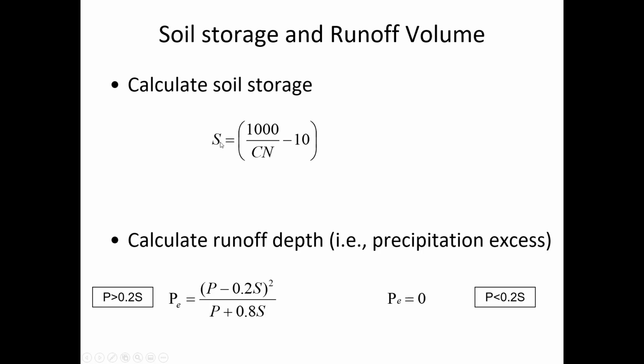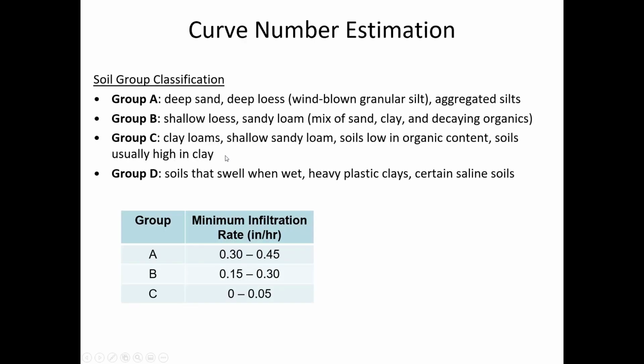So this is the NRCS equation, and this is simply how you calculate S. S has units of inches. Sometimes we use SI units, and you'd have to convert from inches of S into SI units, but these curve number tables are based on traditional units of inches for depth. So this is jumping ahead a couple of slides. If you've got them printed out, this may be material that's a few slides ahead, but I thought maybe it fit better in today's lecture.